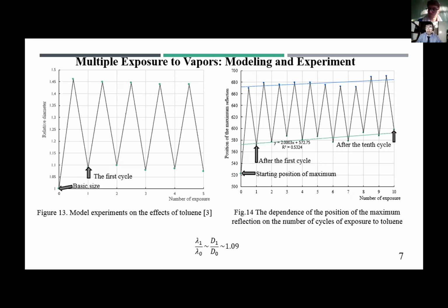It was found that after eliminating the exposure, the position of the photonic bandgap is almost completely recovered. This fact allows carrying out chemical cycles of online environmental monitoring. However, with exposure to aromatic solvents, sensor degradation is observed, but its linear character should be noted. This slide shows the changes of the spectrum of the reflected response from a photonic crystal under the cyclic action of toluene on its surface.